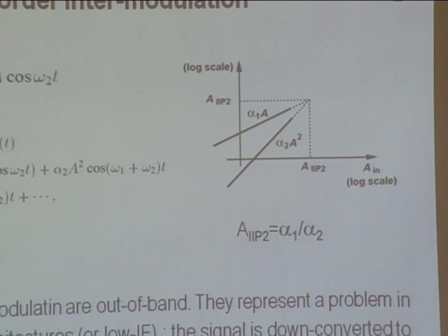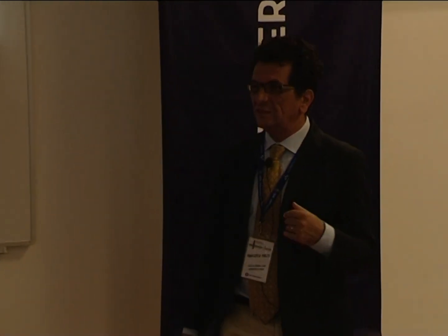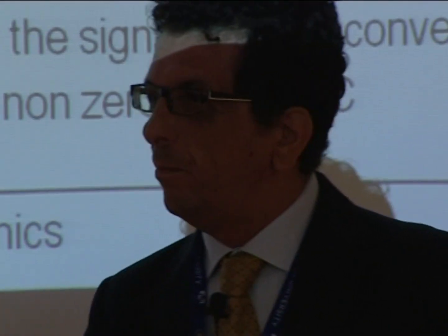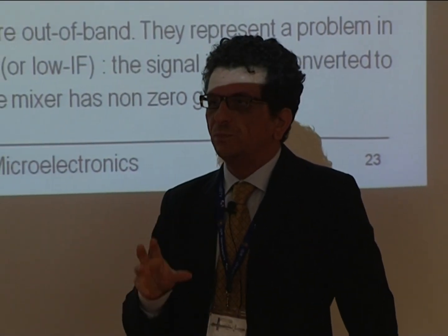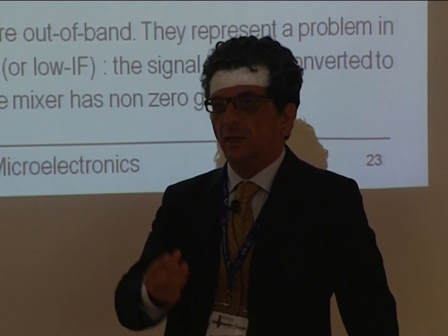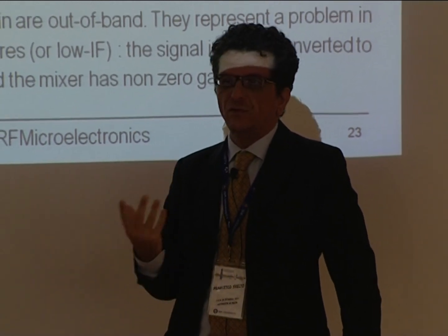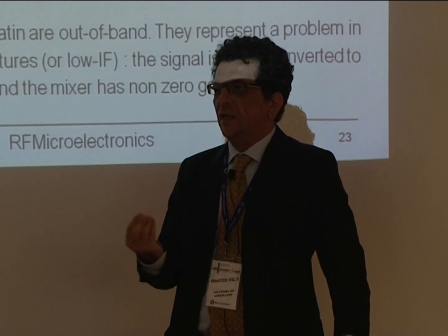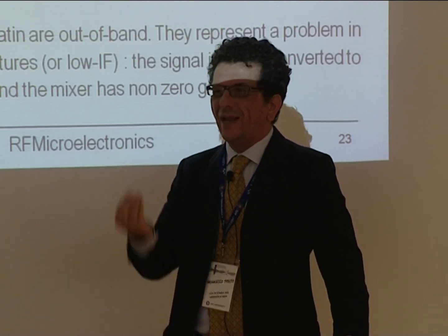And this is an important metric in direct conversion architecture. It's not much important in super heterodyne, in heterodyne, but it's important in direct conversion architecture. Why? Basically because when you generate second order components, think about a sinusoid, any frequency. If you square it, you produce a component which is proportional to the second harmonic and also has a DC component, okay? Correct? So sine of omega 1 t squared means 1/2 plus 1/2 sine 2 omega 1. So this 1/2 is at DC.